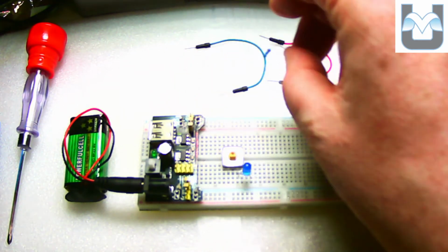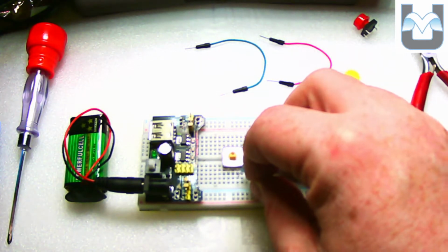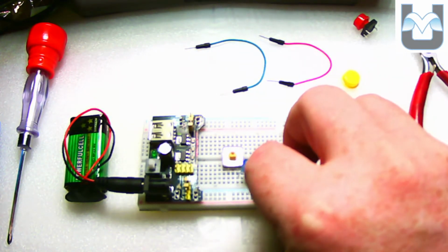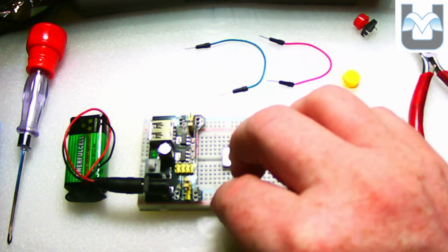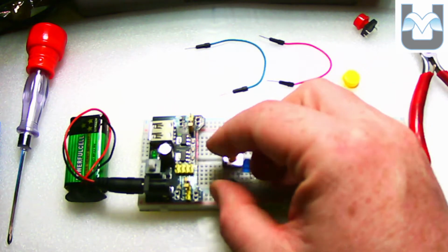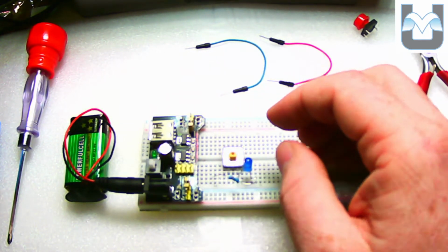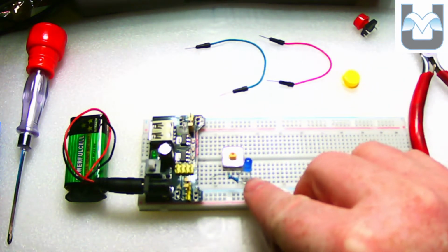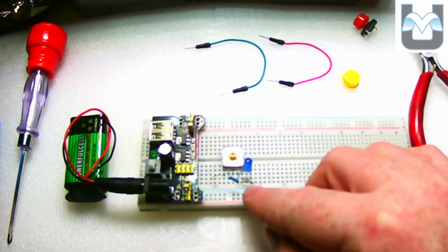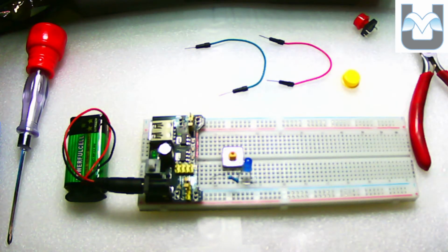Okay, I'm going to take my resistor. I'm going to do exactly what we did in the LED section. I am going to hook it up into the same terminal strip as the LED. I'm actually going to run mine back this direction. Make sure your leads don't touch when you're doing this, but there is nothing stopping you from putting things together in pretty tight quarters. If I touch this resistor lead to the other side of the LED, I might be in for a bit of trouble. That wouldn't be too good.